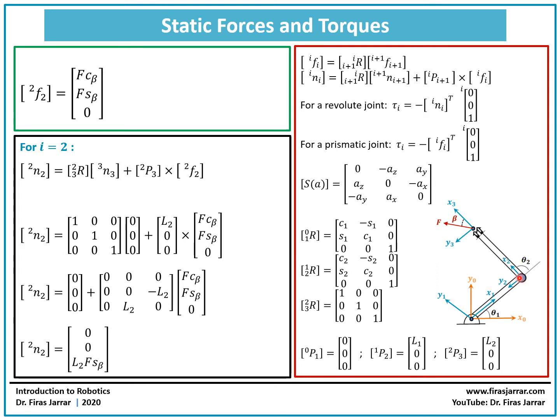If you really put them together, what we have here is as if we are moving the force vector to here. But we know that when you move a force vector, you change its line of action, so you also have to compensate with a moment.